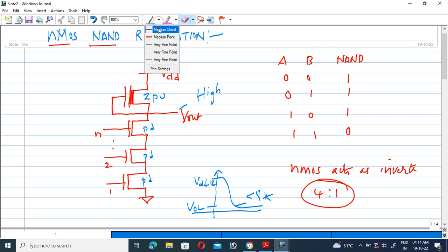When a logic 1 input is applied to the nMOS transistors, the corresponding nMOS transistors are in a short circuit condition. Therefore, it acts as a short circuit path from VDD, through the drain terminal, to ground. Whatever the high voltage is, it passes to the ground. Therefore, the output voltage is equal to 0. So it satisfies the criteria, right?